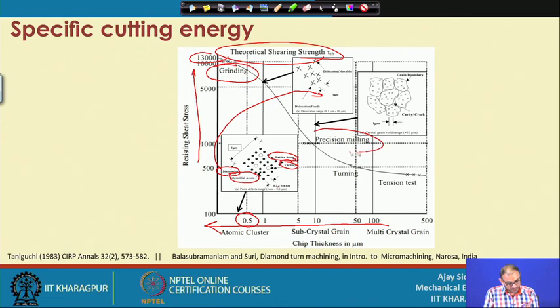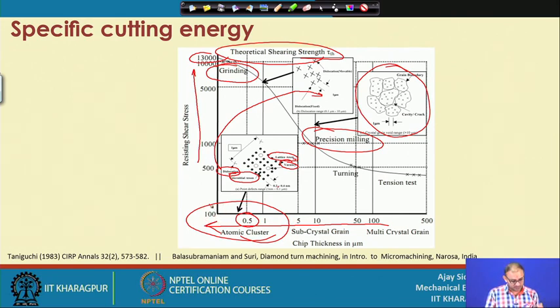That is what is happening in our precision milling or precision micro machining. We are actually working in this particular area, because we are talking about the grain and the defects within the grain, but we are not going into the range of less than 5 micron or so, because after that many other things may happen. The precision and resolution of your machine tool itself will create a lot of problems, and we have another limitation related to the cutting tool geometry, because you cannot scale down a cutting tool beyond a certain limit. After that, the material of the cutting tool also plays an important role, such as the grain size and how you compact those things and make them more stable.